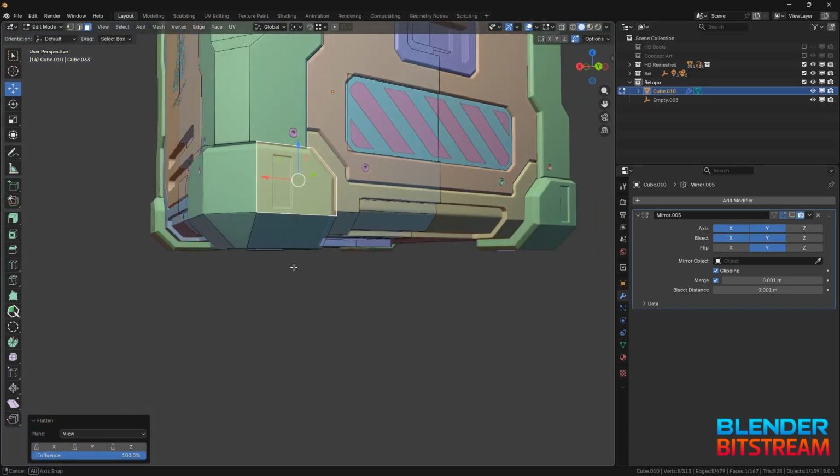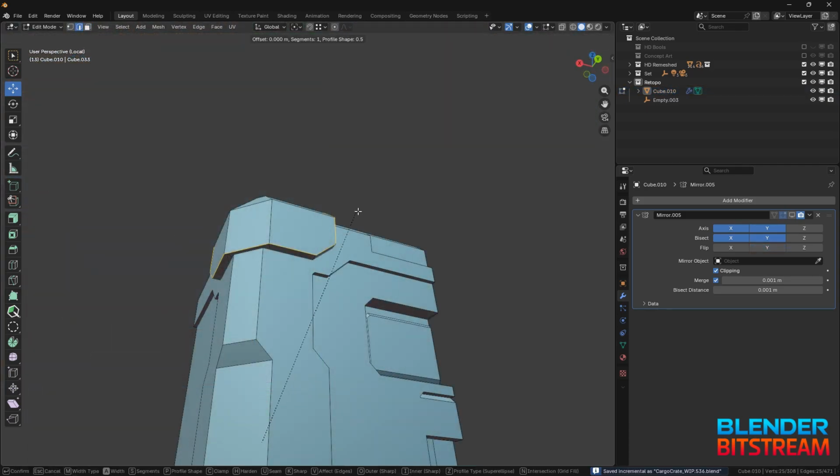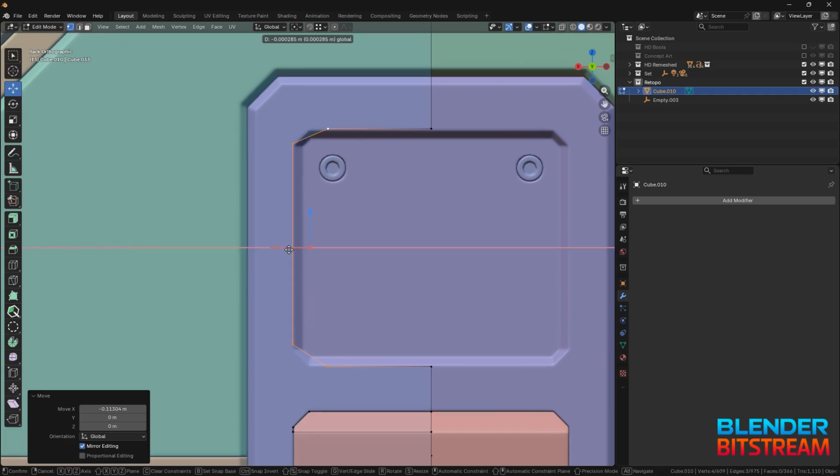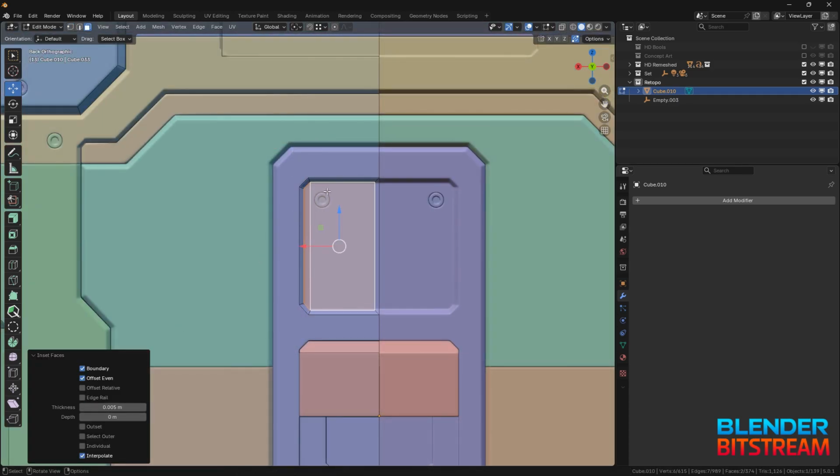Also, I recommend you install the Loop Tools add-on, as flatten and spacing tools are super handy during this process. It's a free add-on and can really help save time. The link to the Blender extension page with the add-on is in the description.